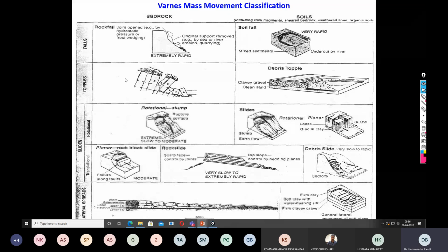Okay, so all these fall under the category of landslide or slope instability. But when you try to determine the factor of safety, when you read about geosynthetics in geotechnical engineering, we normally address the lateral spreads. Provision of geosynthetics is one of the best ways of avoiding lateral spread. While in slides, we talk about rotational and translational. So these are the few things we deal with in the slope stability chapter.